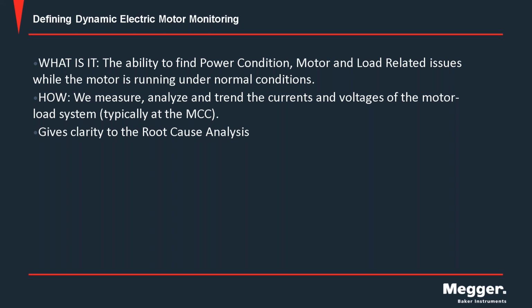So that's going to help us understand the whys, right? The root cause analysis. Why is my motor failing? Not only am I at end of life, but how did I get here? And so that we can proactively go out and make our plants better so that our motors can live in an environment that's more suited for a longer life. So I like to say that when starting a program, I want to buy a static tester so I can identify motors before they fail, but then I want to buy a dynamic tester so that I can identify those areas that are causing my motors to fail.